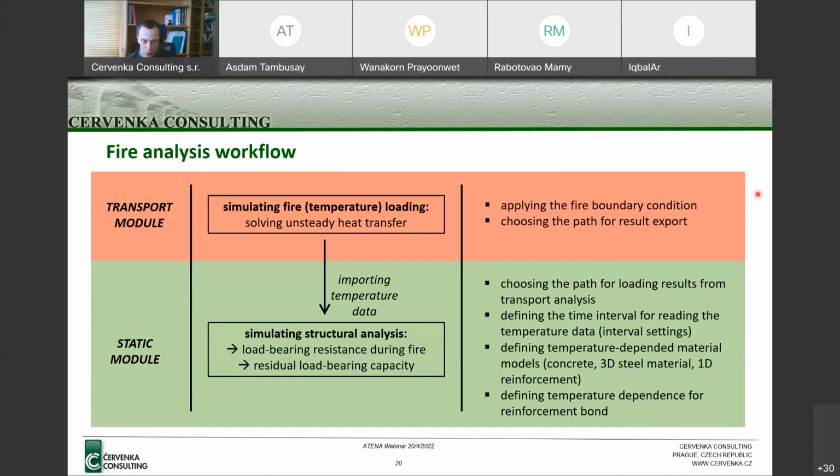So if I want to use the model code, I don't know if there is any straightforward way to do it, but maybe I can fit the interface properties based on the results. I mean I can simulate the load test to obtain the relationship and fit the interface properties to obtain the relationship according to the model code. I hope it was understandable. So what I mean is to model the interface using interface elements, and try to fit their properties in order to obtain the result according to the model code. That might be the way. So now let's go back to the fire analysis.